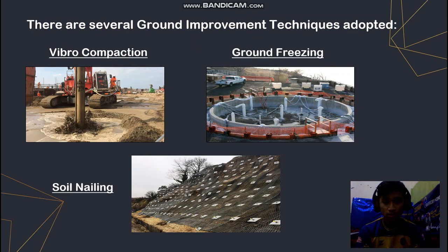Normally, there are three ground improvement techniques adopted. First is vibrocompaction, second is ground freezing, and lastly is soil nailing. For vibrocompaction, this method is suitable for port construction and marine projects. This method is also the most economical and sustainable.